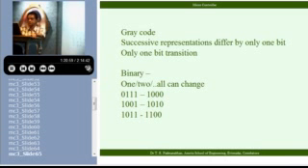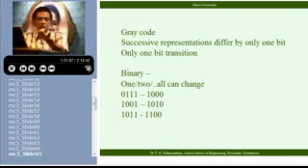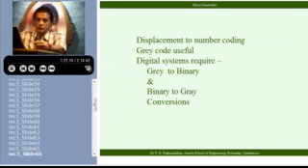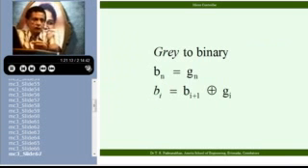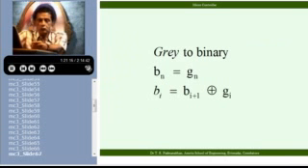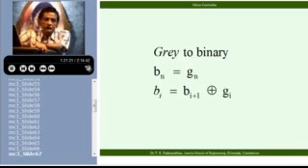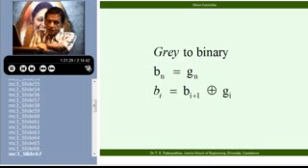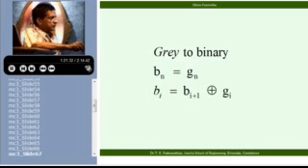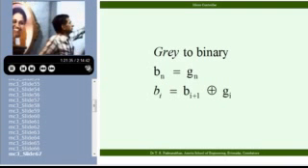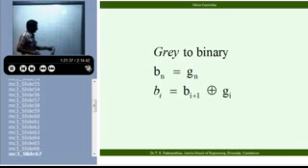Of course, this we discussed. So it is always useful to know the conversion from binary to gray and the reverse. Now, you can just check whether you are getting this. Please put the binary code and the gray code separately. You will find that the highest bit, the most significant bit, is the same for both of them. In the binary code, if I call that bit Bn, and in the gray code Gn, the highest bit is always the same.